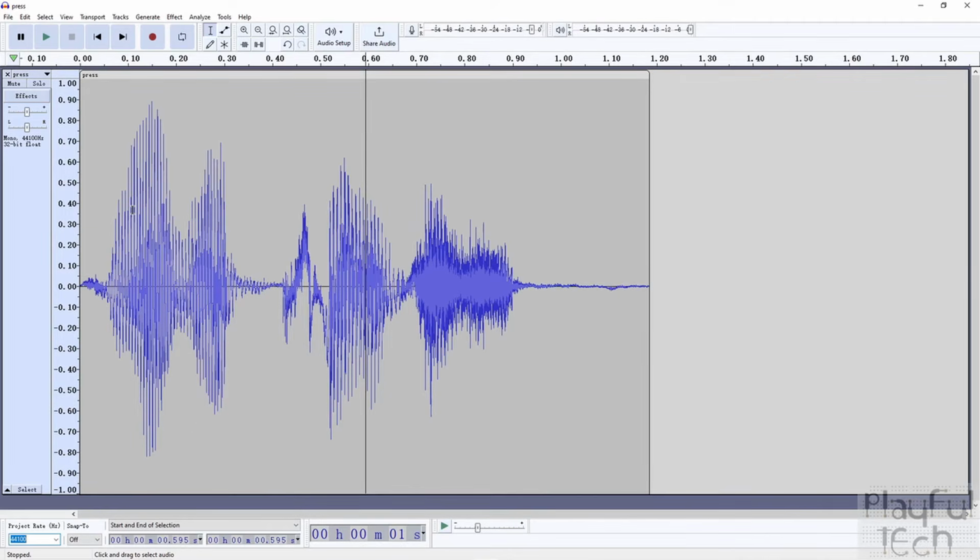So if you start off with a blank disk, a blank SD card, or an empty flash memory chip, and you save the file 00001.mp3, it will be assigned the index 1. And that's the file that will play when you press the first button in trigger mode, or where you issue a serial command to play back the first file. If you then copy over a file called 00004.mp3, it won't be assigned the index 4, it will be assigned the index 2, because it's the second file on the disk, whatever the file name is.